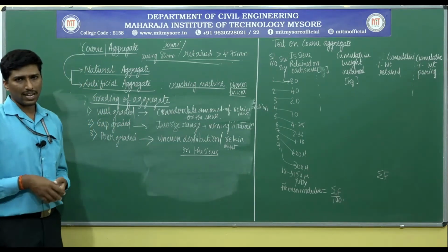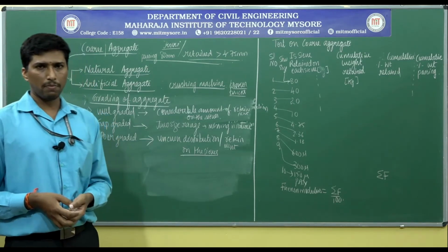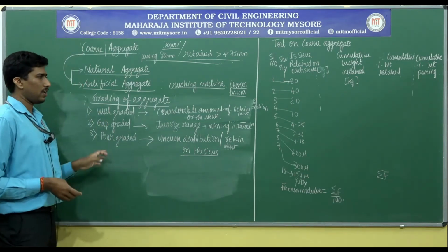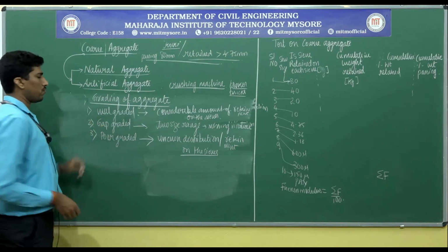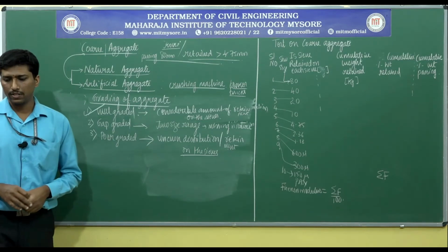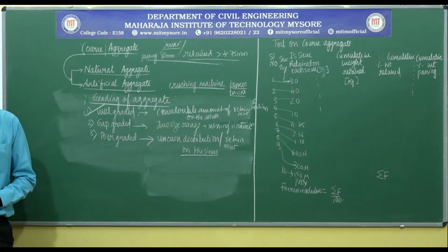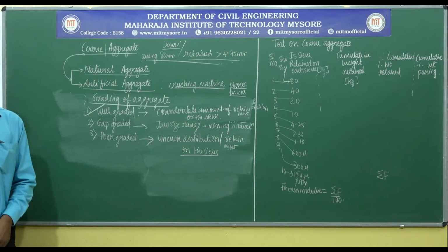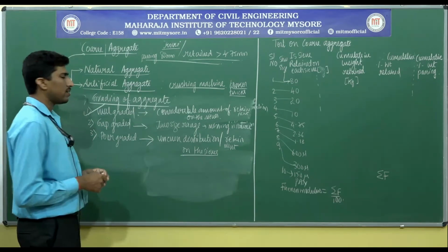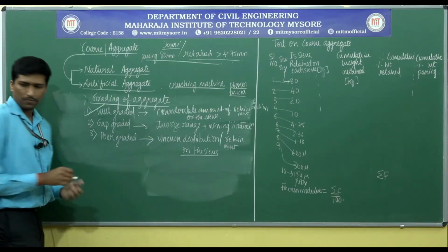That kind of aggregate shall not be utilized for the concrete mixing purpose or making purpose or designing aspect. It will be detrimental in nature. Therefore, always you need to go for using the well graded kind of aggregates. Clear with this concept? And moving on to the next part of the concept, it is related to the test of the aggregate. Before the test of an aggregate, why is the grading much more significant? Let us get to know.